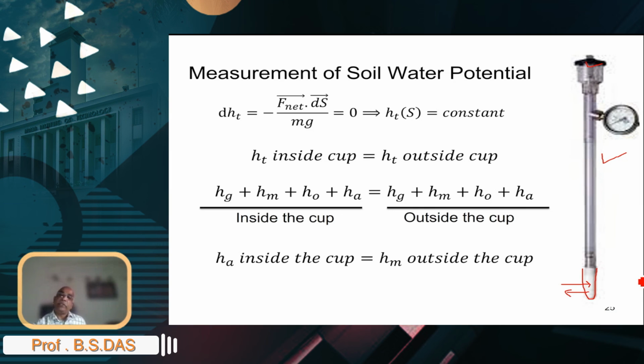So if you put this in soil, and the soil is dry, of course water will start coming out in all directions. As water comes out, the top is sealed, and therefore it would create a vacuum inside, because air cannot pass in to neutralize that vacuum.